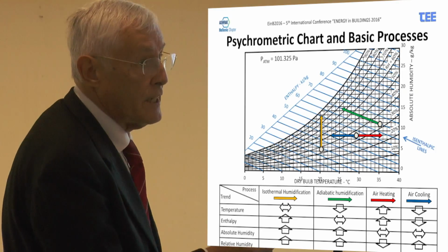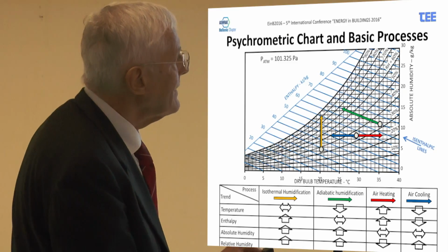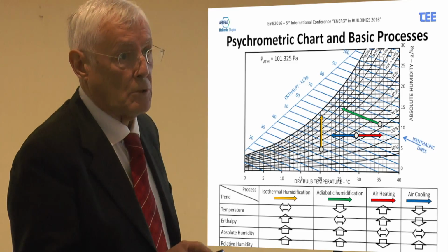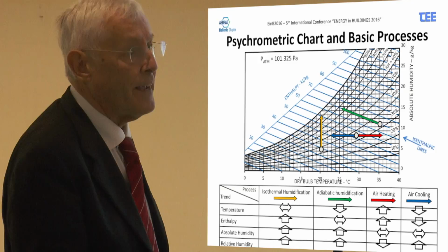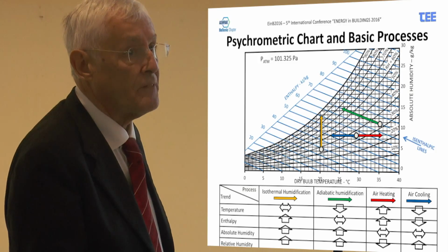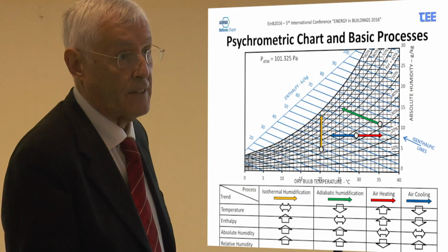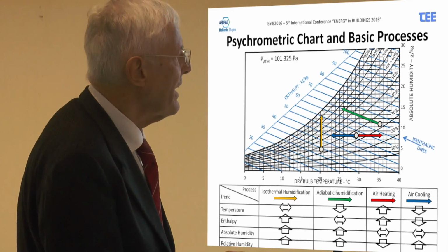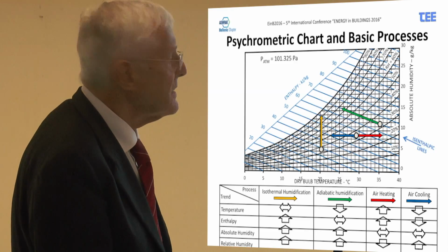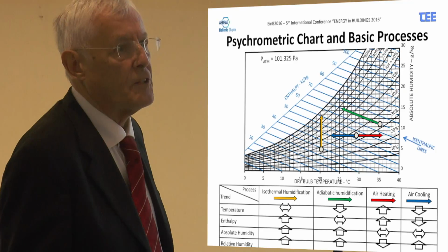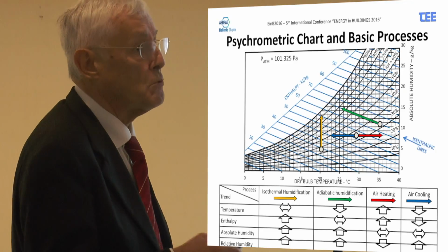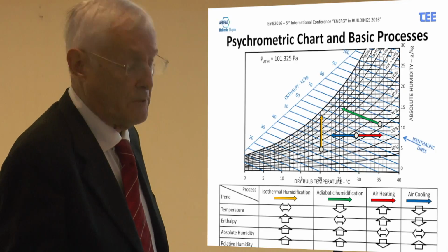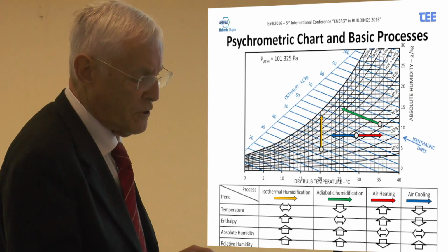And just to give you an idea, for each 10 kilograms of water per hour we evaporate, we get approximately 7 kilowatts of cooling effect without employing any energy, as happens with a normal refrigeration system, which in this case would require 2 kilowatts, for example. So it is very important for energy conservation.